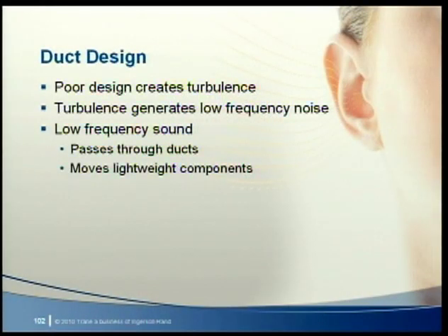Unfortunately, the equations don't apply to the many creative configurations that are developed on the job site. It is unknown how changes in duct size that occur during a turn, abrupt transitions, or closely coupled duct components perform acoustically. Experience has shown that a convoluted air path can create considerable low-frequency sound. In many cases, the sound energy is below 63 Hz and may even be below the audible range.